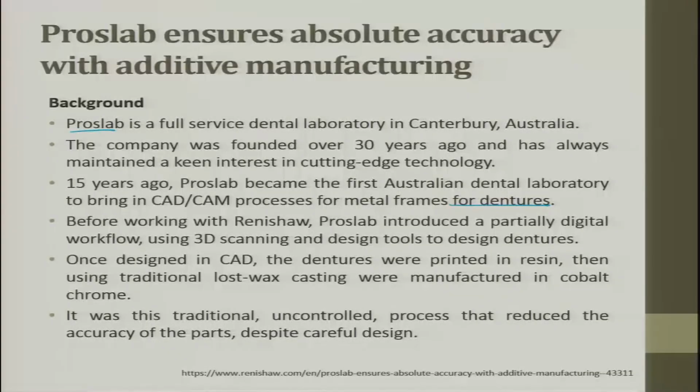Now, with the existing CAD data, the solid model, they are pushing that solid model data into rapid prototyping machines or rapid manufacturing machines, wherein you use powder as the starting material or liquid as a starting material, process the building block and get the part. So, earlier they used it for CAD scanning and identifying the process and quickly developing the process plan and then getting the output. Now, they have moved into additive manufacturing and rapid manufacturing.